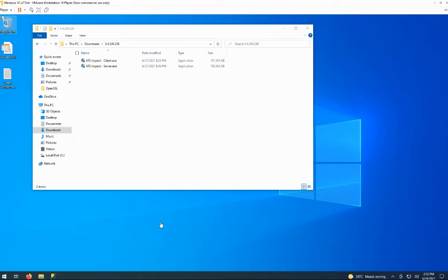Hello. During this training video, I would like to run you through the installation process of ATS Inspect. We will be installing a version close to Service Pack 7 on a fairly clean VM with SQL 2019 already installed. So this is going to be one VM with Inspect and SQL on the same machine.